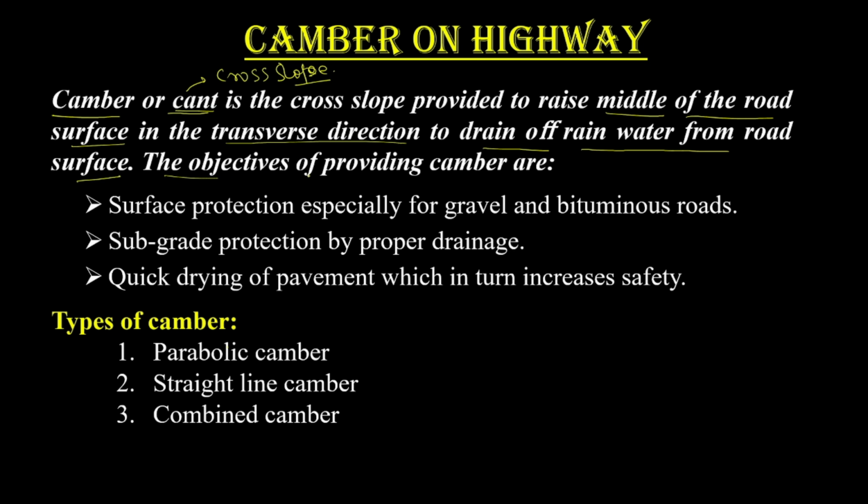The objectives of providing camber are, so why we are providing: first, surface protection, especially for gravel and bituminous roads; subgrade protection by proper draining; and the quick drying of the pavement, which in turn increases safety. So one by one we'll discuss.